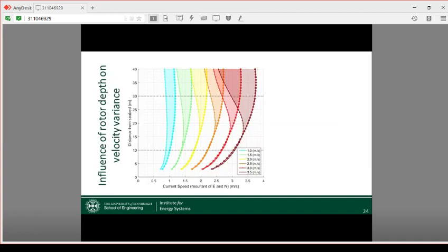And just to give you an example, these are some graphs that show the tide or velocity variation at different states of the tide for the flood and ebb tides at the EMAC site. And if we put a turbine in the position that the Alstom turbine, a floating turbine, was in, then this is the kind of velocity variation that the turbine would see. If we look at the turbine that was actually deployed, the Alstom turbine, then this is what we see. And if we look at something that's mounted on the sea bottom and is close to the bottom in, say, the OpenHydro turbine, then this is the kind of thing that it will see. In each case, you see different mean velocities, but you also see completely different variations in the velocity.